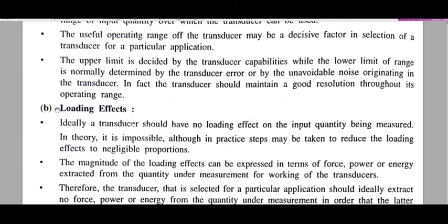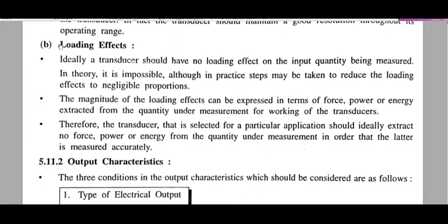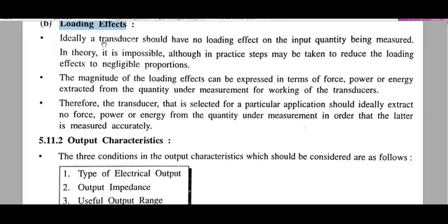Okay, then next one, that is the loading effects. What is the loading effect on the characteristic of a transducer? Now we can see that ideally a transducer should have no loading effect on the input quantity being measured. In theory it is impossible, although in practice steps may be taken to reduce the loading effect to